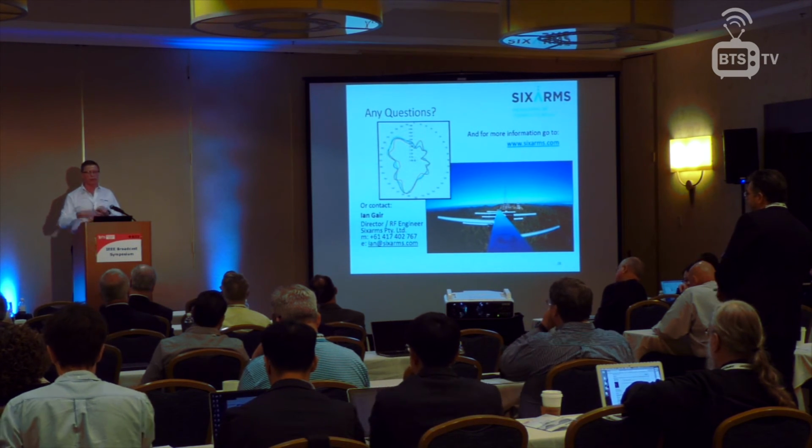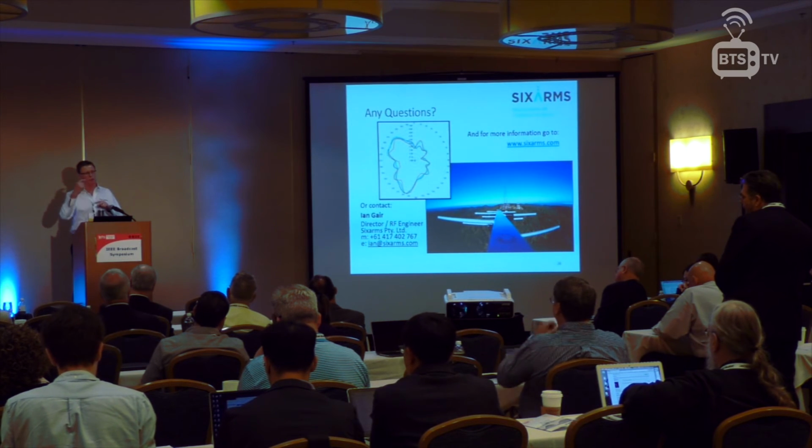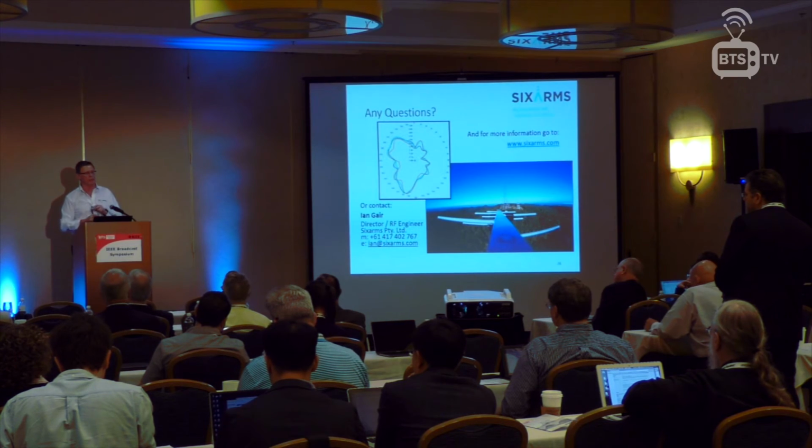Well, that's one way of doing it. Or the other way is that you're getting two signals. One is the incident signal, and the other one is a reflected signal, which is arriving later than the incident signal. So you set up the spectrum analyzer with a gating front end, which only accepts the incident signal and rejects anything arriving after a period of time.